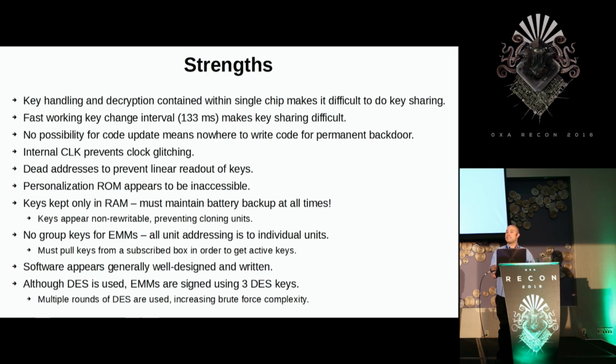The dead addresses that they put in the middle of the key space is very nice. This prevents a linear readout of keys and would really stop a whole class of attacks against it. The personalization area in ROM that they use to write the unit address and the seed keys initially seems to be accessible once they complete that mode.